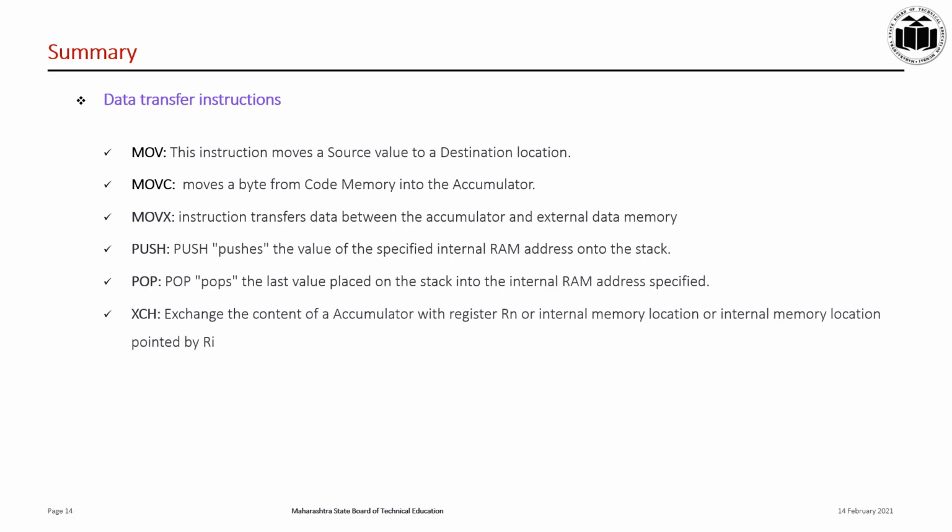Exchange. Exchange the content of accumulator with register Rn or internal memory location pointed by Ri. XCHD. This instruction exchanges the lower order nibble of internal memory location pointed by Ri with accumulator.